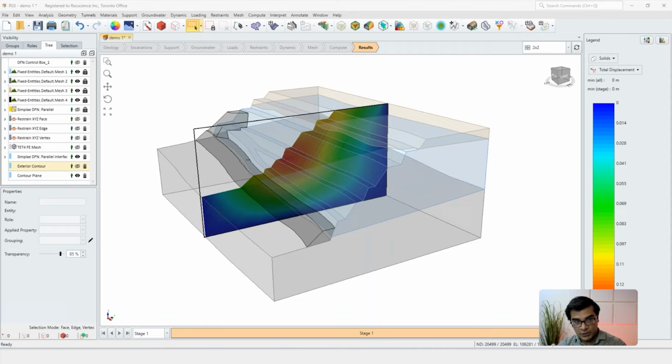When all of them are done and you did all the repair, add the DFN in the last step. Because if you assign it earlier, then the divide all process, if you bring more geometry into your model, can increase the time. So the best time is to add the DFN at the last step, and after that you do the final divide all for the joints that you just added. Okay, thank you very much.